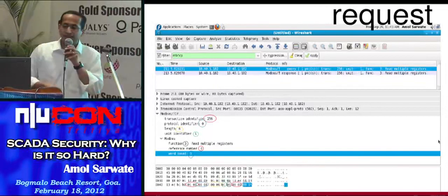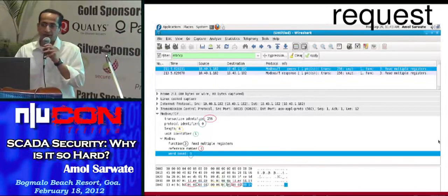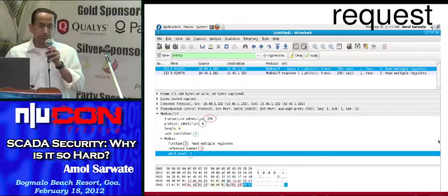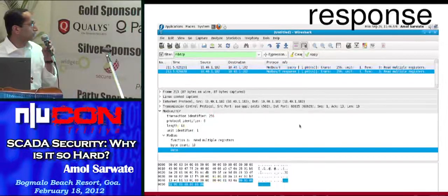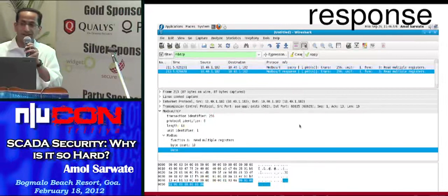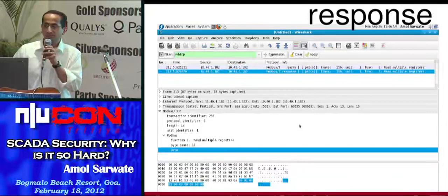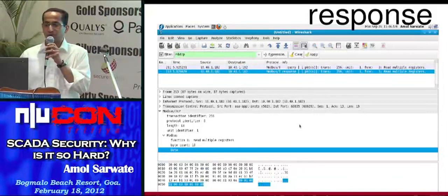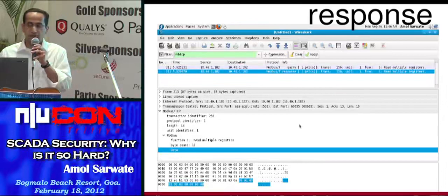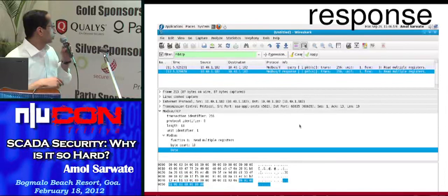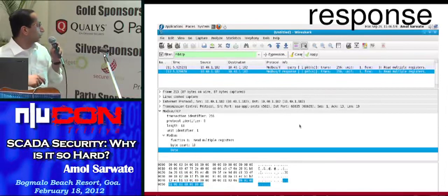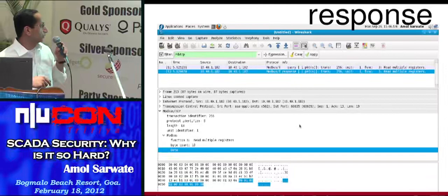So what we see when we send this request is this on Wireshark. Modbus is a pretty famous protocol, and usually when we work on protocols, we have to write protocol decoders for various sniffers because the sniffers don't support them. But Wireshark and I think most protocol decoders support Modbus by default, so we didn't have to write any special decoder for this.